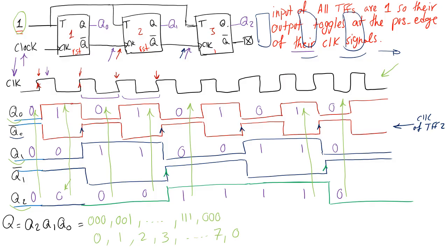Well, you have to somehow detect that you have reached 500, and we're going to learn that in the next lecture. You can think of it yourself, and it's not really hard to make that detector. The moment that you detect that we have reached 500, your detector block sends a reset signal to the reset of all of these T flip-flops, and they all reset to 0. Okay, so that's how you make sure that this thing is counting to an arbitrary number that you want.